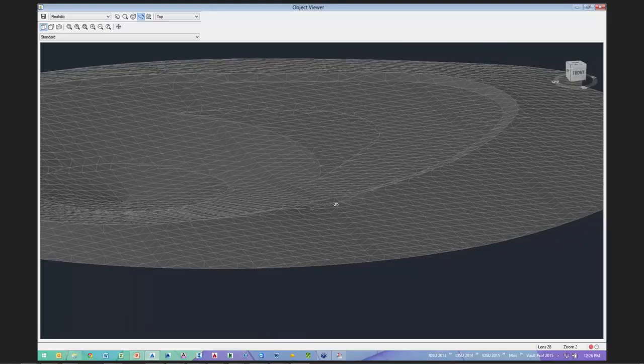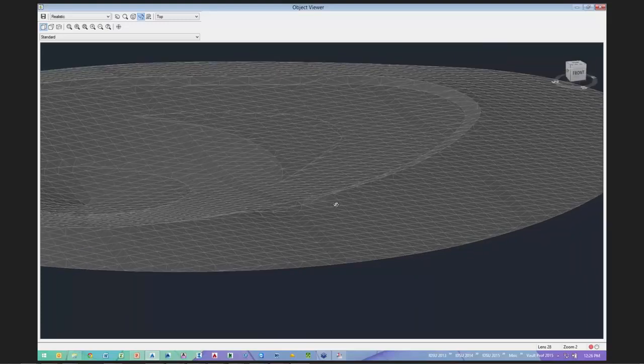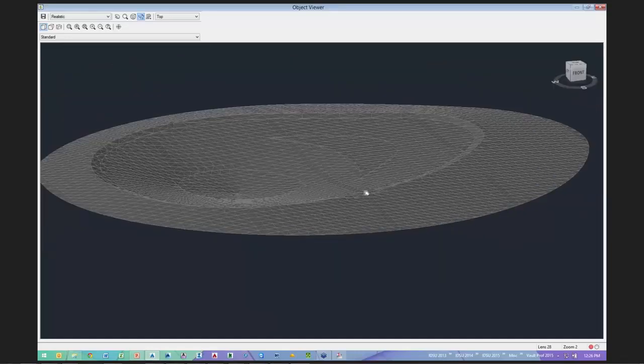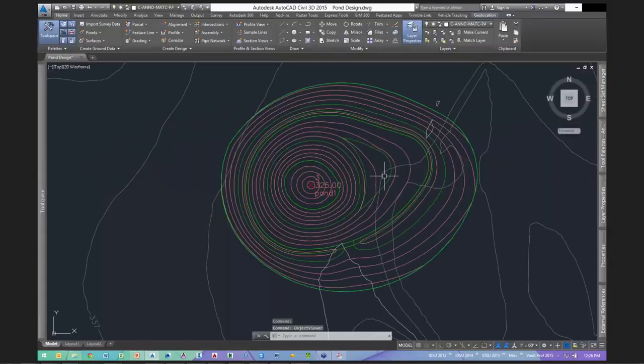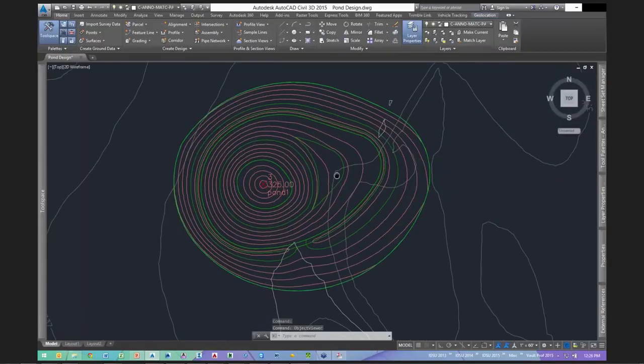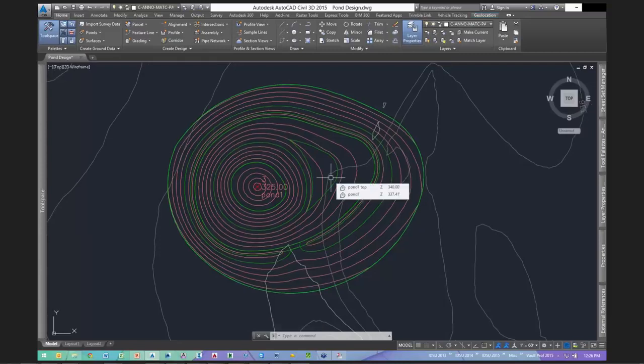So you kind of have to play with it a little bit. Did we need 5? Maybe 10 was enough. This adds data to your drawing. Okay, so a small pond like this, not a big deal, right? That took no time, perfect looking contours, works great. Huge site, don't just smooth the entire site. Do it in areas where the slopes are constantly changing, something like that. If you have typical slopes, sheet drainage in a parking lot or something like that, and it's just a constant slope, you shouldn't need to do smoothing like this.